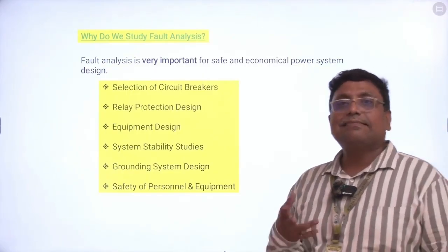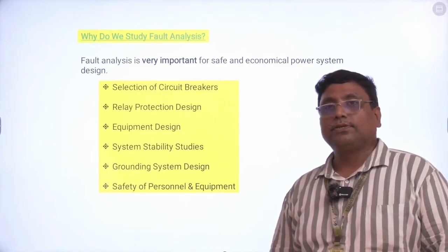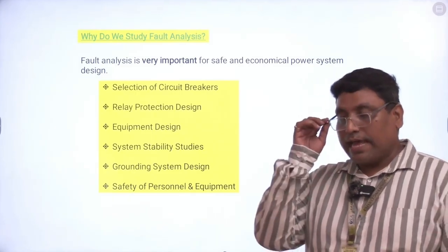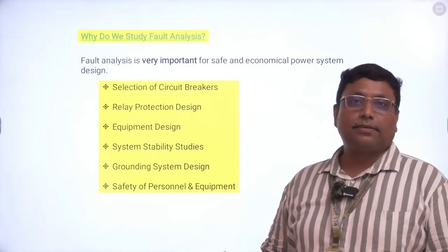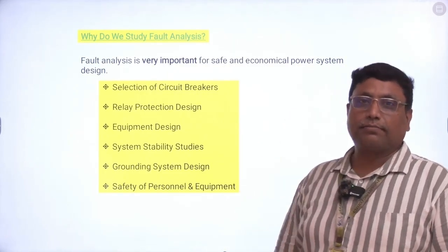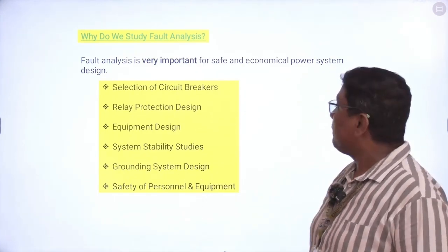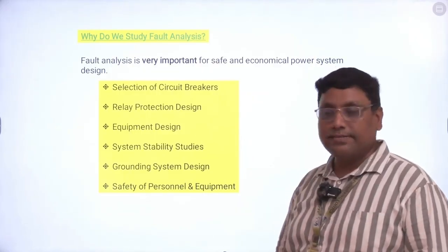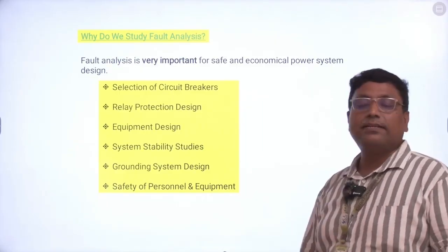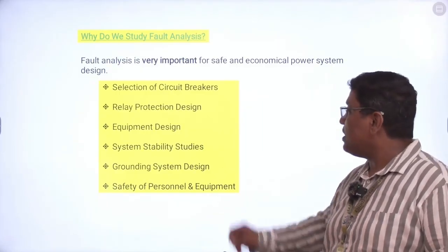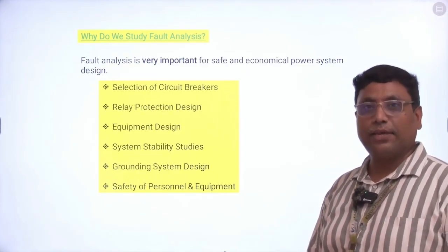So what is the necessity of fault analysis? The purpose of fault analysis is the selection of circuit breaker, relay protection design, equipment design, system stability studies, grounding system design, and safety of personnel and equipment.